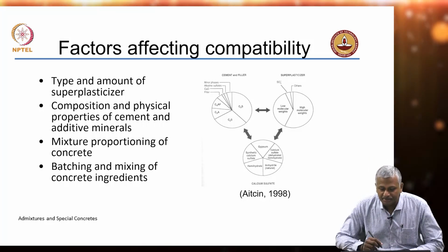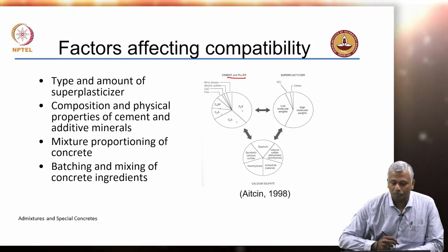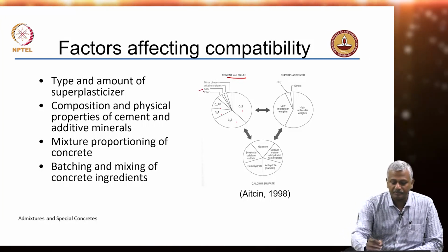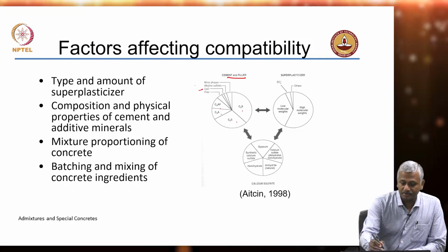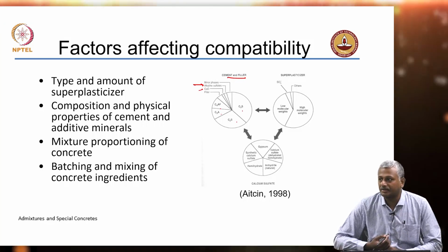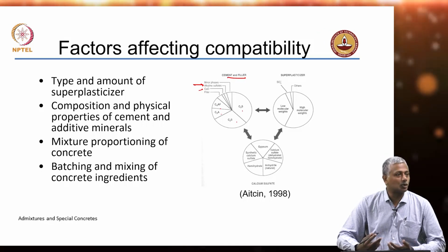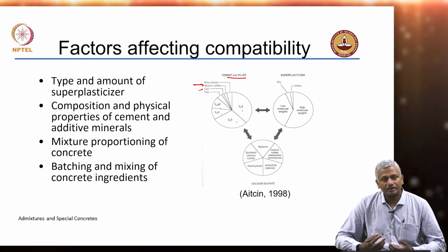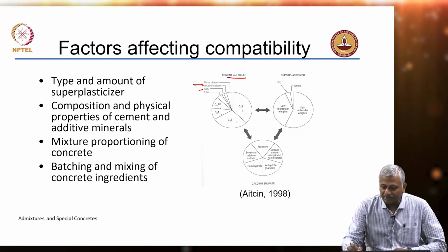Okay. So, just to put this in a nutshell, if you look at the cement and filler, of course, you know that cement is composed of all of these 4 major compounds. It has got other minor oxides including free lime, sometimes free calcium oxide, right, and it's also got what is the most critical component, the alkali sulfates, sodium sulfate, potassium sulfate and the likes. Okay. Again, these are sulfates and these are highly soluble sulfates. So, you have to take that into account also while deciding on your early age chemical constituent of your pore solution. You then have the superplasticizer.